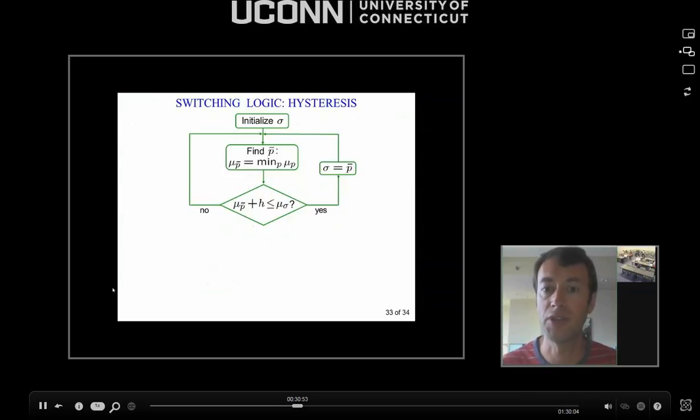And this is where the technical meat of the analysis is, where the hysteresis switching logics are concerned. So the first type of result that is known is the following: if your family of plants, or the range where the unknown parameter lives, which is the script t, is finite, if the monitoring signals are all monotonically increasing and one of them is bounded, then the switching stops in finite time, which is quite an interesting result.